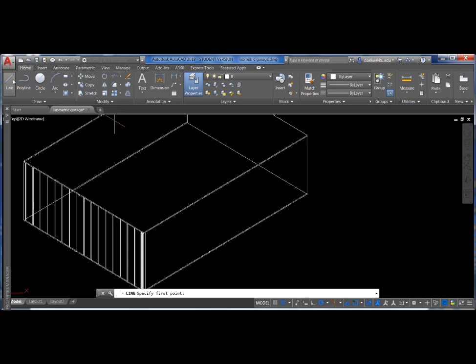So this gives us, in our 30-foot wall with a 1-foot overhang, a 16-foot rafter on each side. So 16 feet times 6 inches is 96 inches of rise. So the rise is going to be in the very center of the building along the 30-foot side.